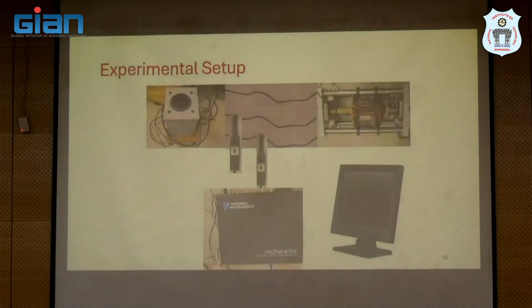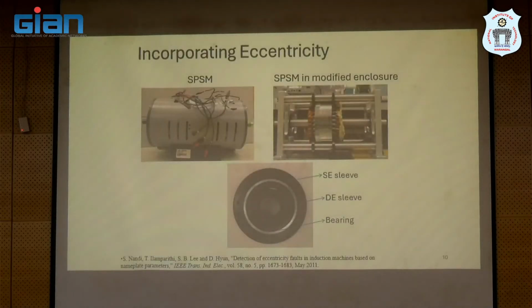The problem with such a setup is that because it's an open enclosure, it's quite dangerous. You cannot have anyone who has no training go and work on such a setup. You may end up losing an arm, sometimes even worse, when people go and work without adequate training and safety. These machines are rotating at high speeds, so you have to be really careful. And because they have open windings carrying high currents, you need to be really careful as well. Accidental short circuits should be avoided.